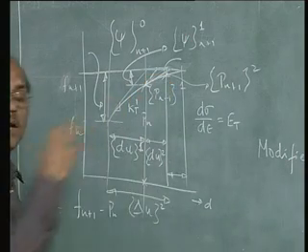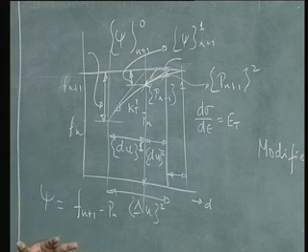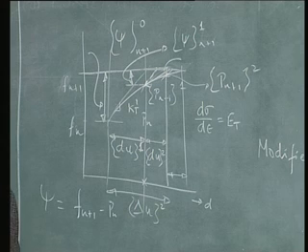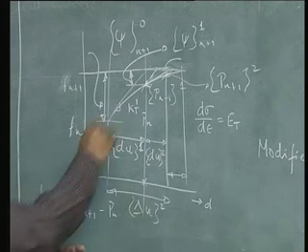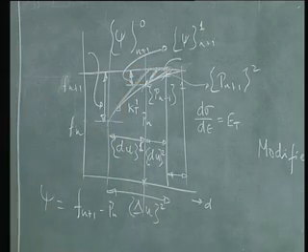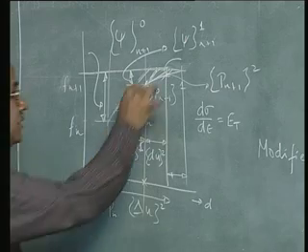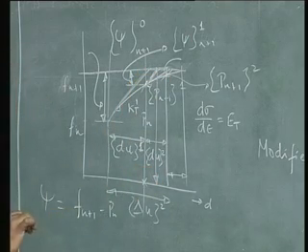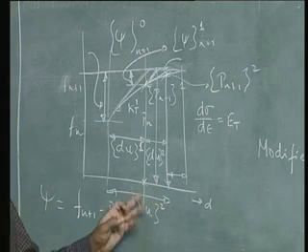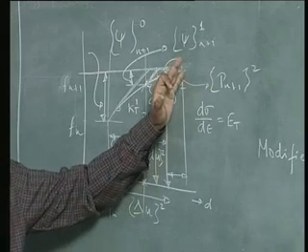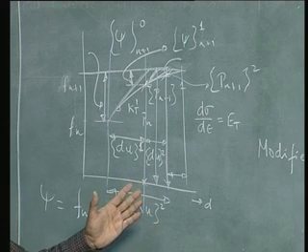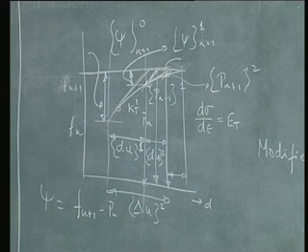Okay. The slope here, I should not say slope, but my tangent stiffness at that point would be parallel to it. Then tangent stiffness here also would be parallel to it. Now, as it is, when I use the tangent stiffness at that point to be parallel to this, that is, this and this are parallel, obviously the next point I am going to hit is this point instead of this point, right. So, in other words, my climb towards the correct solution is going to be slightly less, or maybe more number of iterations it may take.